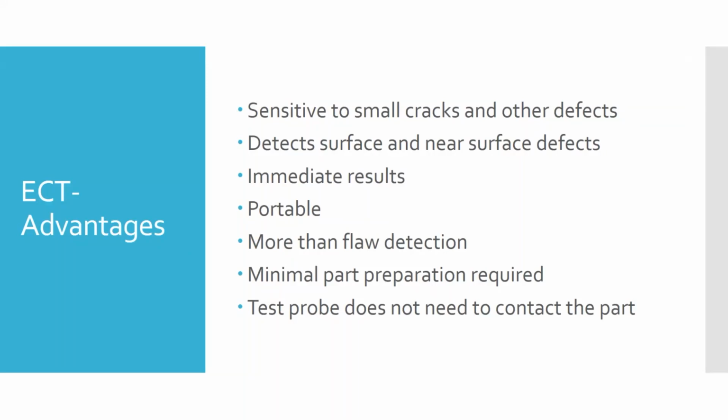The results are immediate. You don't have any kind of dwell times like you do for liquid penetrant. There's not a lot of setup involved. And like something like X-ray, you don't have to develop film, although most X-ray has gone to digital detectors now. So you get immediate results. It's portable. That unit you saw in the picture at the beginning is handheld. It can be handheld, or some of them can use neck straps or that kind of thing.